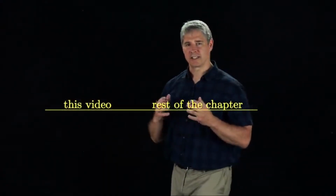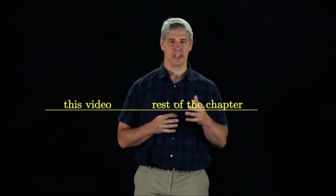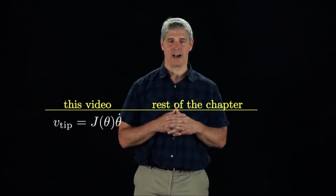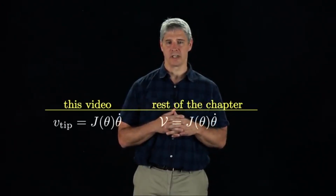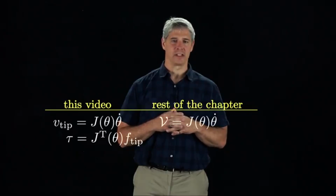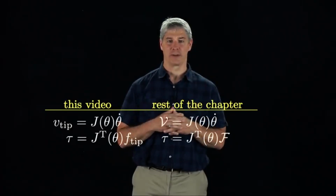So this video summarizes the important concepts of Chapter 5. In the rest of this chapter, we translate these concepts to twists and wrenches. In particular, in this video, we represented velocities as V tip, the time derivative of coordinates. In the remainder of the chapter, we represent end effector velocities as twists, either in the S-frame or the B-frame. In this video, we represented end effector forces as F tip, forces dual to V tip. In the remainder of the chapter, end effector forces will be represented as wrenches, either in the S-frame or the B-frame. In the next video, we derive the Jacobian when the end effector velocity is expressed as a twist in the space frame S.